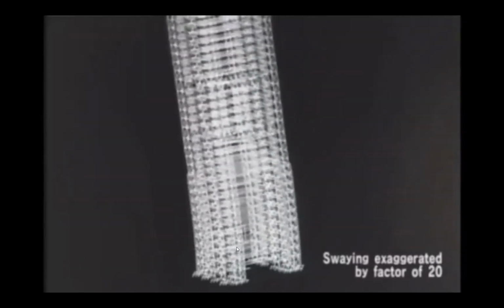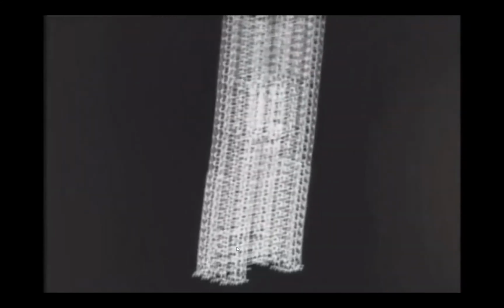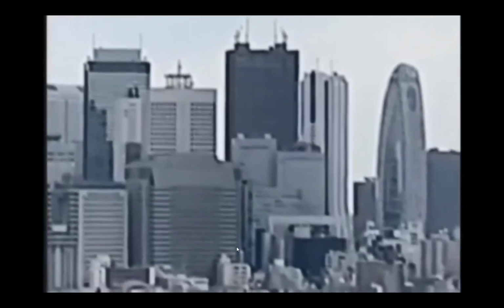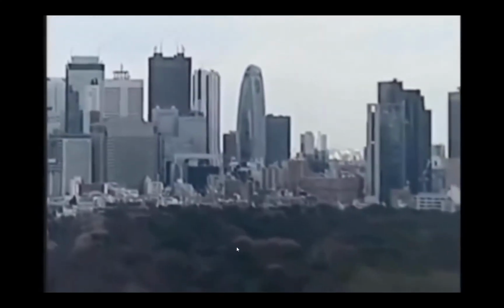At the beginning of the tremors, it sways gently at first, and then gets more and more violent. The top floor swayed back and forth around 60 centimeters, and this continued for more than 10 minutes. Here is a shot of the Shinjuku high-rise district during the earthquake. The footage here is corrected for the shaking of the camera itself. When the video is played sped up, the significant side-to-side swaying becomes clear. The megaquake caused many buildings to sway for a prolonged length of time, resulting in unexpected damage.